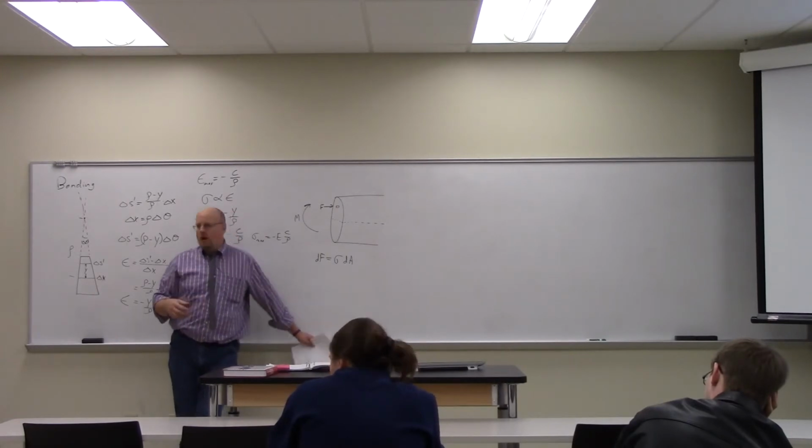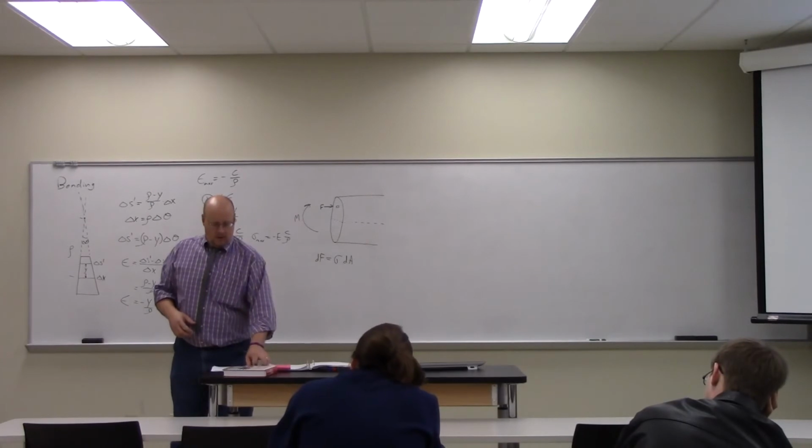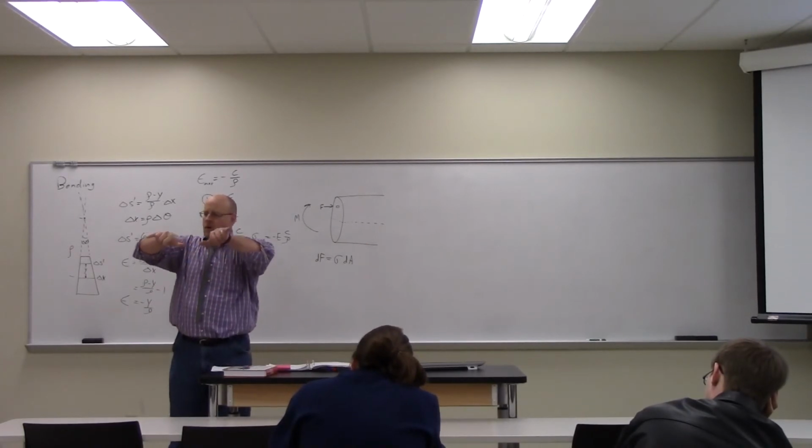So when you bend a bar like that, your hands are each applying a couple. You're applying an upward force and a downward force that are equal and opposite, but separated by a distance. Those are applying bending moments. Okay.